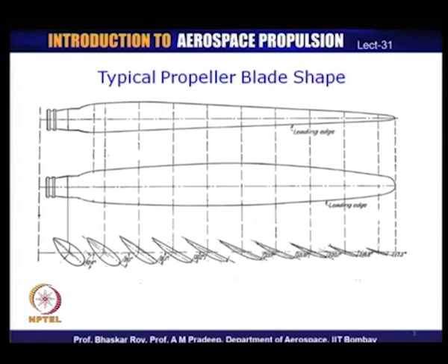So, you need a high subsonic aerofoil, which is normally a thin aerofoil, to keep the drag low, otherwise the drag would mount very fast. A thick aerofoil which you use near the roots, if you use near the tips, would create an enormous amount of drag at that high speed, and as a result the propeller efficiency would be extremely low. So, you need to create an aerofoil which has a very high lift by drag ratio.